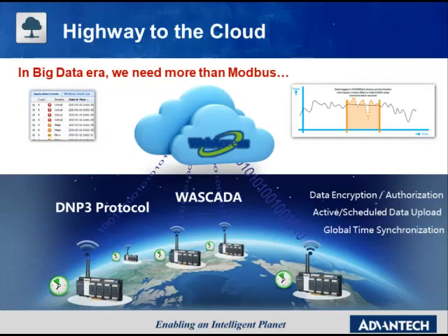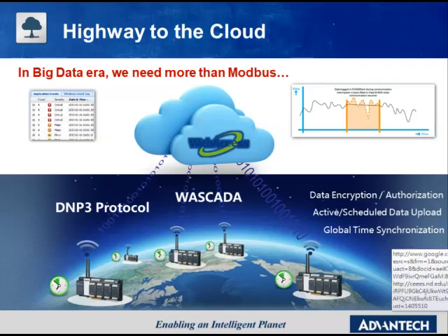Unlike the traditional RTU, which may only support one or two types of proprietary protocol, ADAM3600 aims to be the intelligent RTU in IoT applications, so it supports lots of different protocols. For example, we support the DNP3 protocol, which supports time synchronization between the master and slave, and the data format also includes the timestamp. With the help of protocols such as WS-SCADA, DNP3, and IEC-104, users could have a higher security level and get more advanced functions.